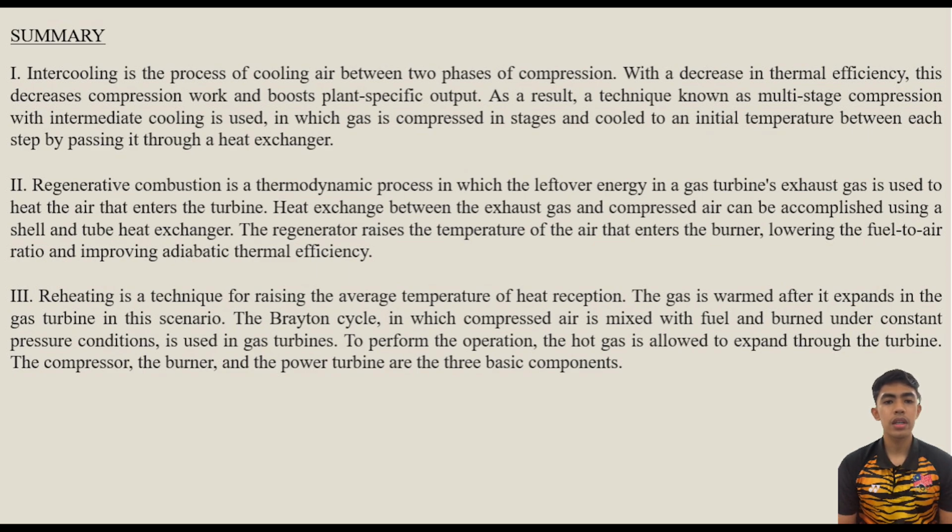Number 2, regeneration is a thermodynamic process that uses the leftover energy in the gas turbine exhaust gas to heat the air that enters the turbine. Heat exchange between the exhaust gas and compressed air can be accomplished using a shell and tube heat exchanger. The regenerator raises the temperature of the air that enters the burner, lowering the fuel to air ratio and improving adiabatic thermal efficiency.